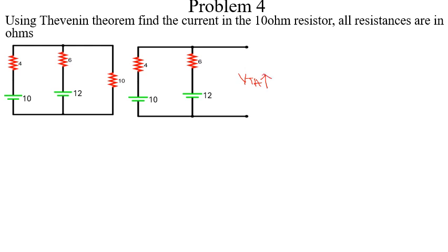So we'll take our loop in an anti-clockwise direction, and here we'll take our loop in a clockwise direction. Basically there are two voltage sources here, and the current delivered from here, when it gets to this node, doesn't split. It all moves back here because there is an open circuit here, so it just moves in one path. There's no splitting.